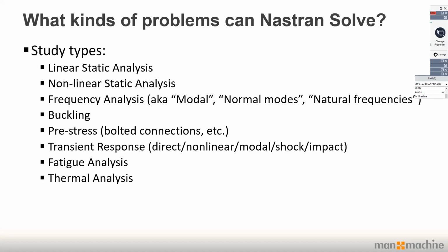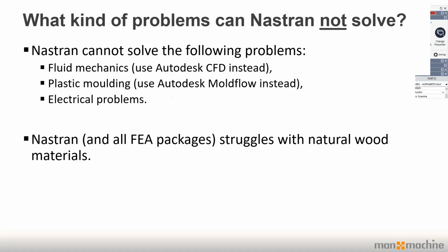You can do frequency analysis, so you can calculate normal modes and natural frequencies. But you can also calculate how your model is going to respond with respect to input frequencies. So you can specify how the structure is going to damp out the energy, input a frequency, and see how it's going to shake. It can also do buckling calculations, pre-stress, so bolted connections, transient response, so basically you can give it an event where different loads are applied at different times. It can calculate fatigue and thermal.